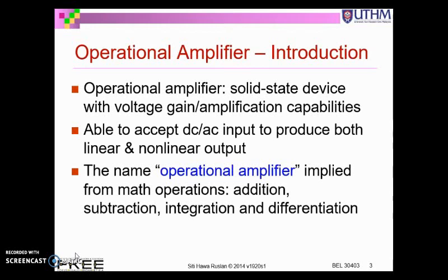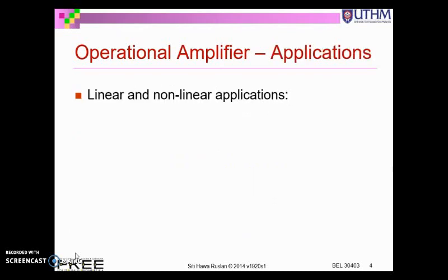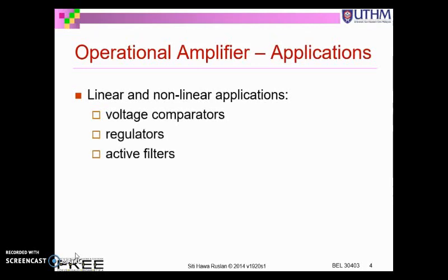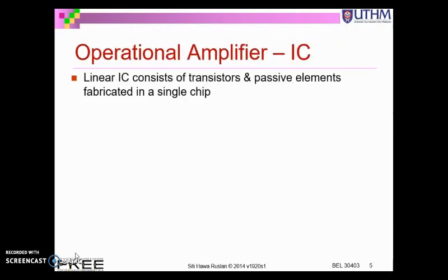And the operational amplifier gets its name from the math operations, which are addition, subtraction, integration, and differentiation. This is when op-amp is used as an analog computer. Okay, that's the short name, op-amp. And we have linear and non-linear applications, for example, as a voltage comparator, regulators, active filters, oscillators, timers, and many others. Operational amplifier is available as an IC, integrated circuit.